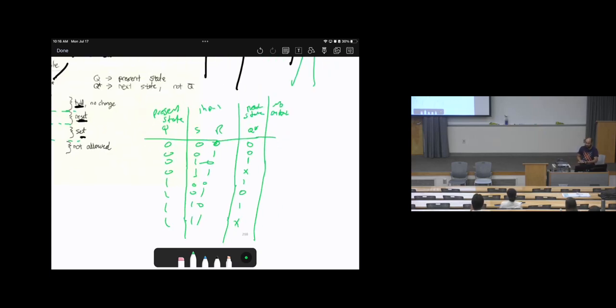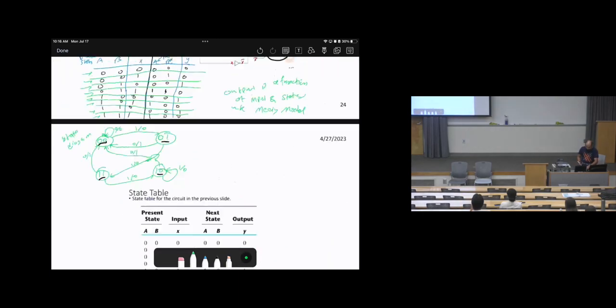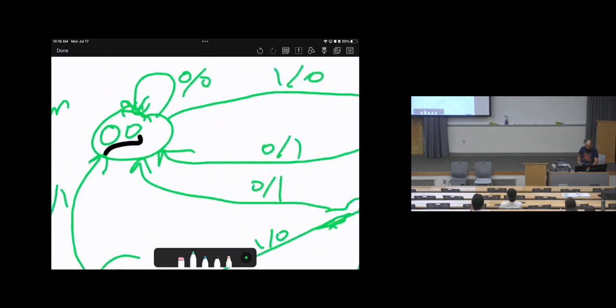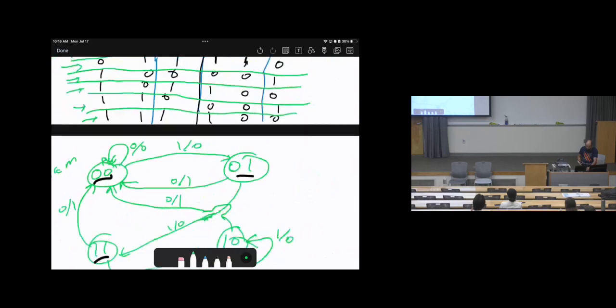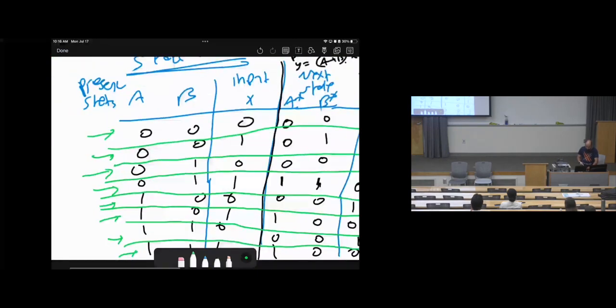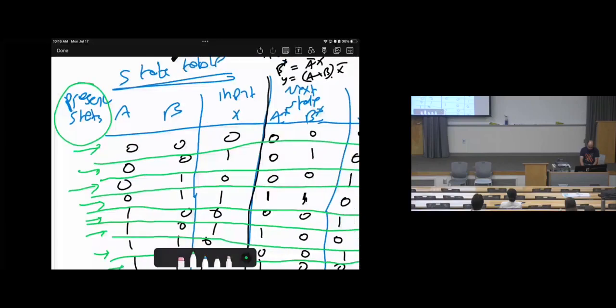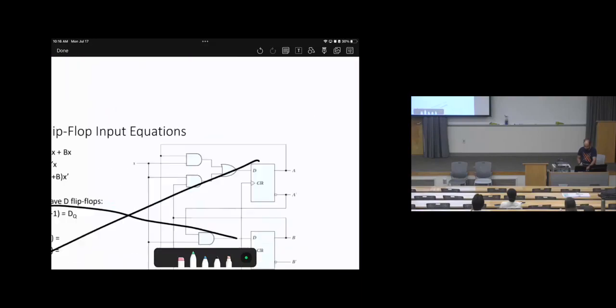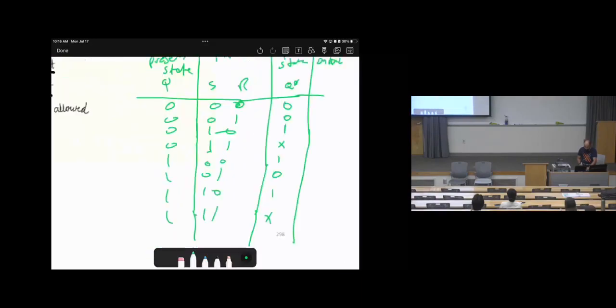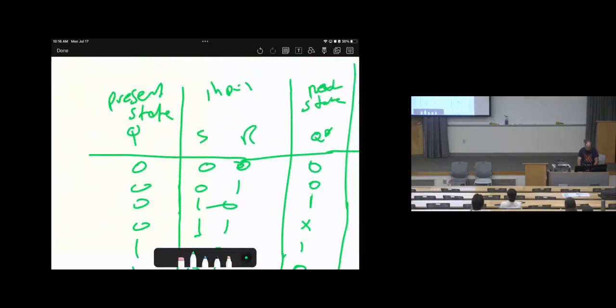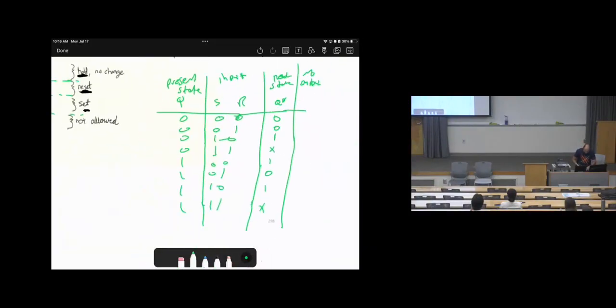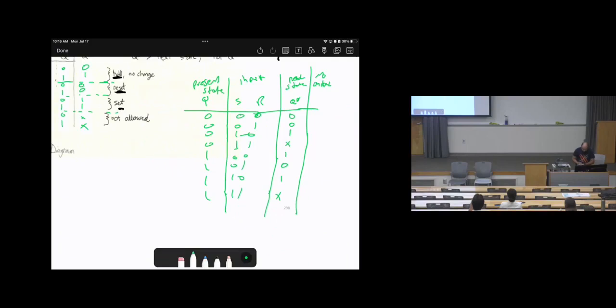What's the point of doing this? Let's go back to the last example, when we did these charts. You'll see the states were in the first part of the truth table, then the inputs in the next part. That's what I did here. I put the present states first, then the inputs next. I made the states at the beginning, so I'm ready to do the state diagram.